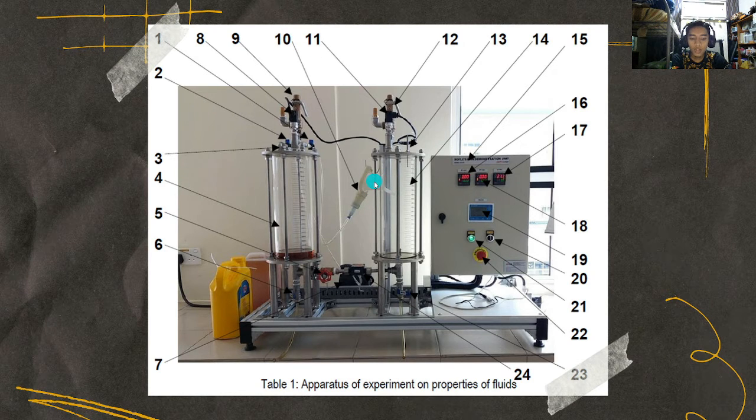We will operate the vacuum hand pump until the volume of air reaches 2600 milliliters, and ensure that the reading of the TT101 temperature does not change. After the pressure reading of PT101 is stabilized, we will record the reading together with the temperature of air, which is the TT101.